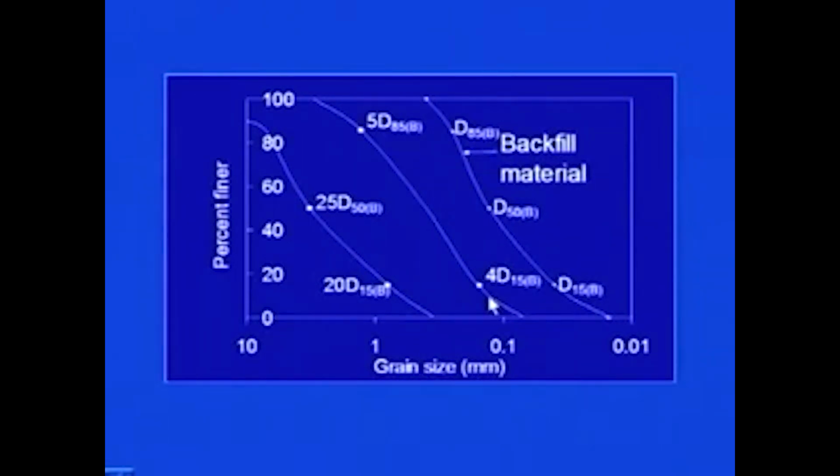But what we keep in mind is that whatever the shape of the grain size distribution of this backfill material is, one must try to follow exactly the same grain size distribution. You see that here this has been plotted approximately in a similar manner as the grain size distribution of this backfill material. So, you do not have to do it like this or any other way.